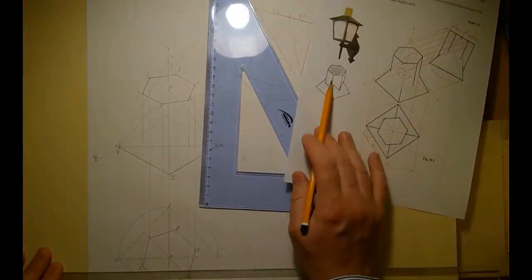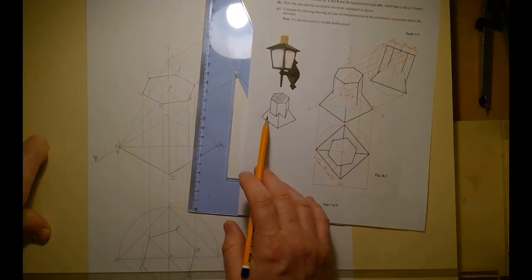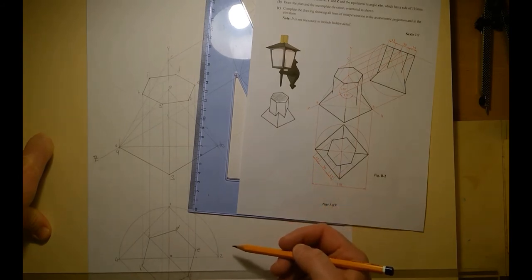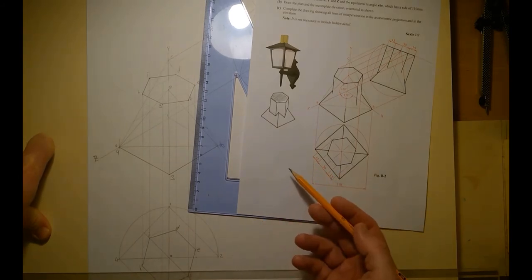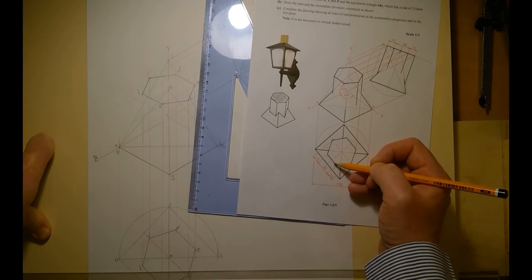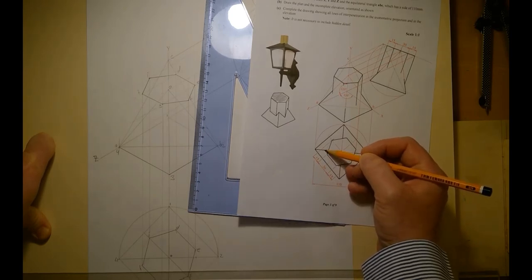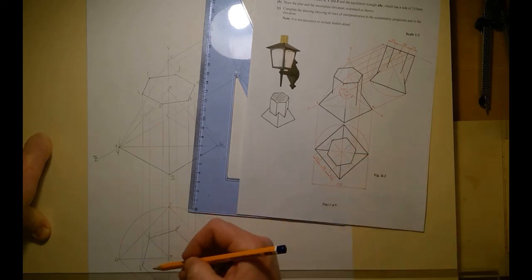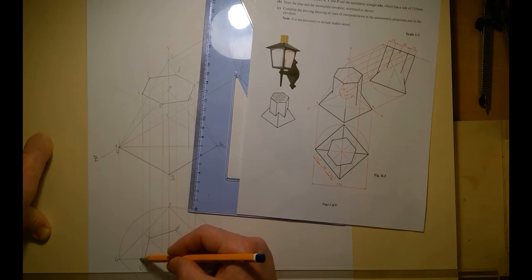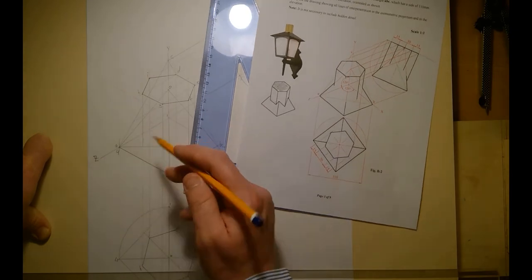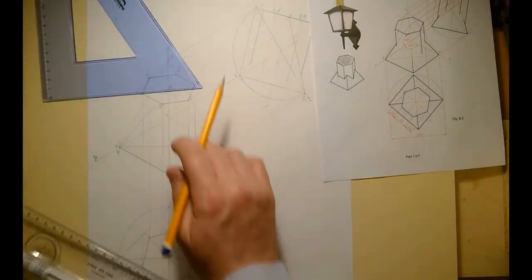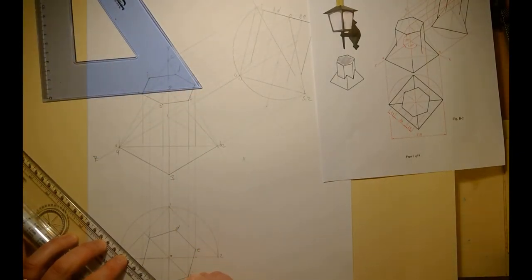Now, what I want to work on now is locating this line here. Okay, so I want to find out how exactly I'm going to do that. So basically in plan, if I were to extend that edge to hit that edge, what I have called 40 at that point. Okay, so if I extend that over, it hits it at that point, I can bring it up then and locate that point in my elevation, or sorry, in my axonometric view.